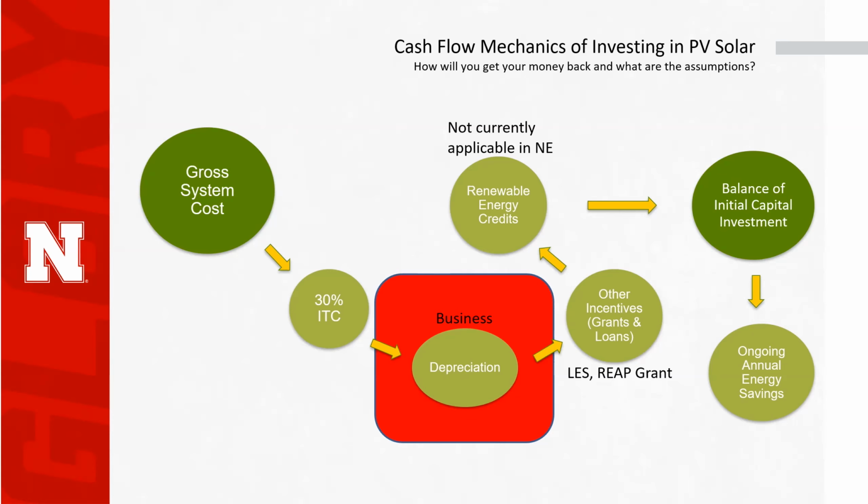Solar hot water is kind of the same way. Solar hot water makes the most sense when you have a high hot water use that's more consistent during the day. The trouble for a single family home is we use hot water in the morning and then maybe a little bit when we're washing at night, but we really don't have a consistent enough use to take full advantage of all the solar heat that's gained. And so a lot of times those systems end up heating up to their maximum by midday, and then they don't do anything the rest of the day because we're not using the hot water system.